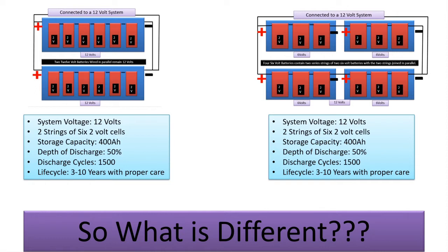So if everything looks the same, what's the difference? Well, if you're choosing to buy flooded lead-acid batteries, 6-volt batteries are considered to be more robust, longer lasting because they were designed to service the golf cart industry. There's a wealth of knowledge available, and there's a long and successful history. These require vented storage, periodic maintenance. They don't charge as fast as AGM batteries, and your cost difference when comparing these batteries will be in shipping and storage capacity. My recommendation is to compare cost per amp hour as a metric to choose the best deal for you, assuming you're choosing quality batteries. Please don't buy budget batteries.